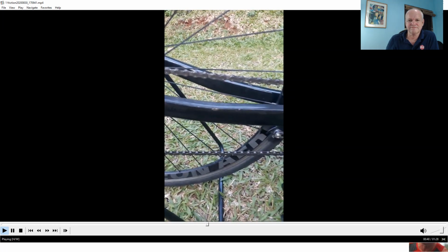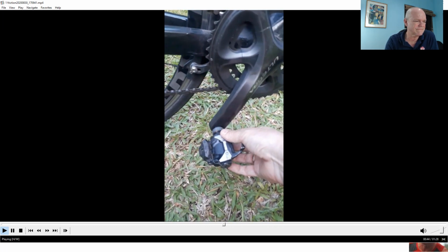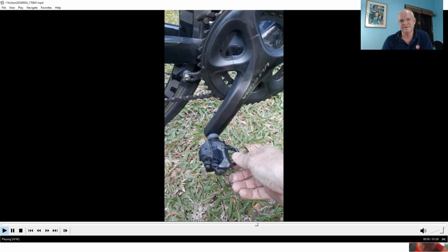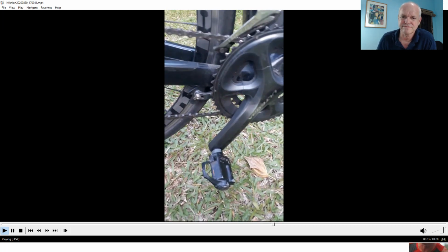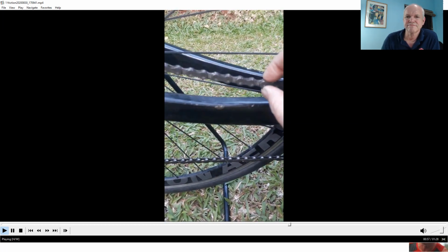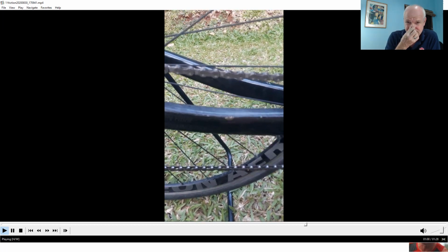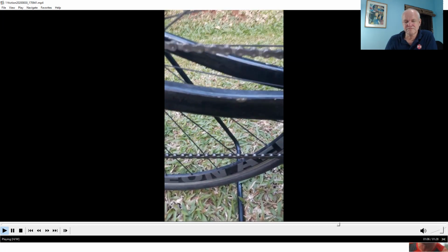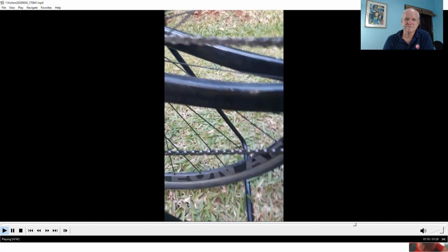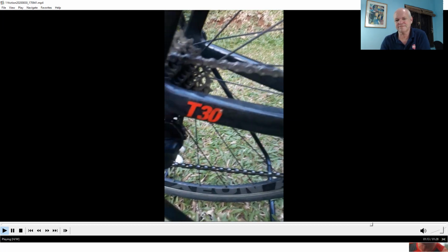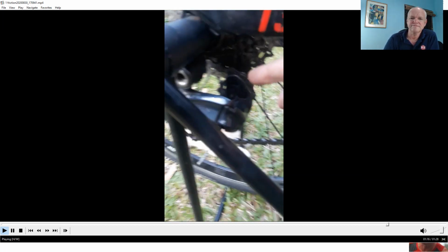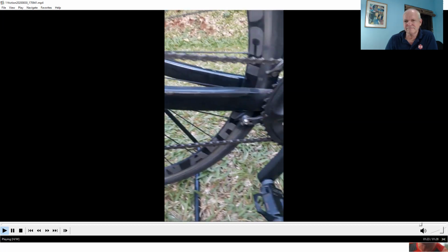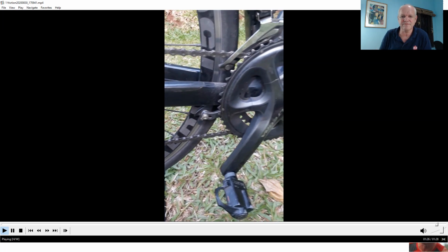Here in the back on the wheel, bottom bracket, here we have bearings in it. So it would be possible to improve, to change the bearings, but that is quite expensive, and the improvement is not so significant. But what is very significant is the chain. Before you are going to race, you should clean your chain, and then you put some oil. You can buy it in a shop, special oil for that. You clean the chain, you clean here everything. You also have to clean here everything. That is not so optimum for a race. So with this, you can significantly reduce your friction.